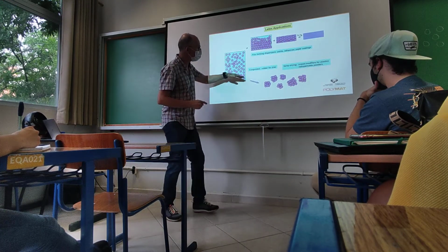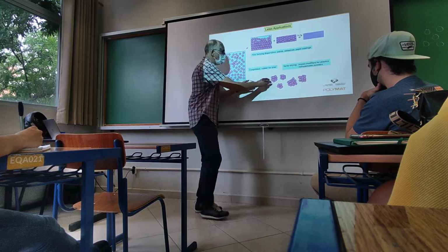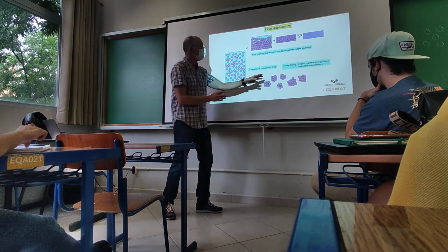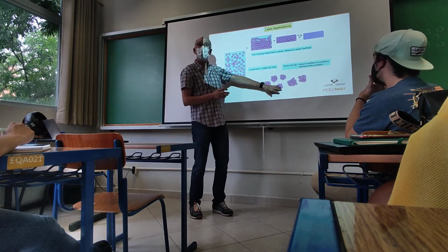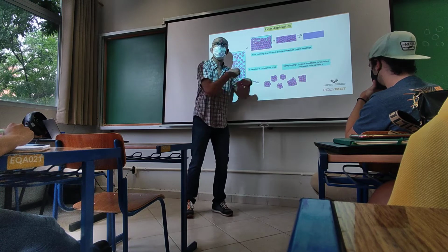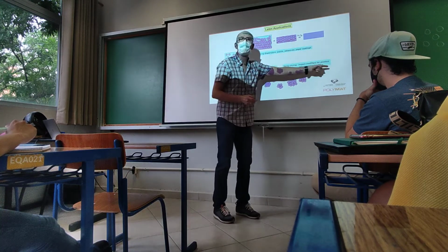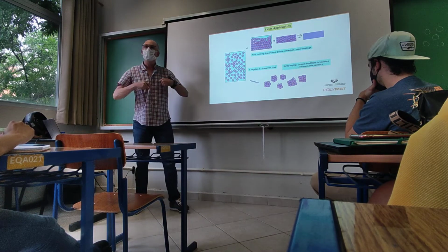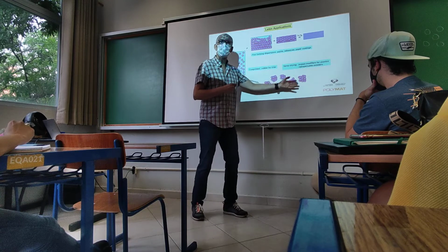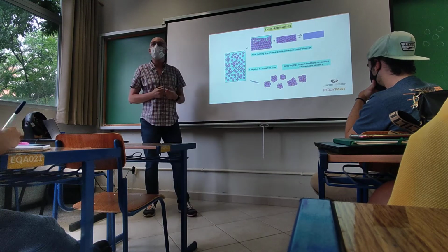The second way is coagulating the latex. When you coagulate, you obtain aggregates, and then these aggregates can be used in different applications. For instance, SBR, you can vulcanize this and produce tiles, for instance, or you can use impact modifiers for plastics. Sometimes plastics which are brittle, you can introduce impact modifiers which are elastomeric, and you make the other polymer better.